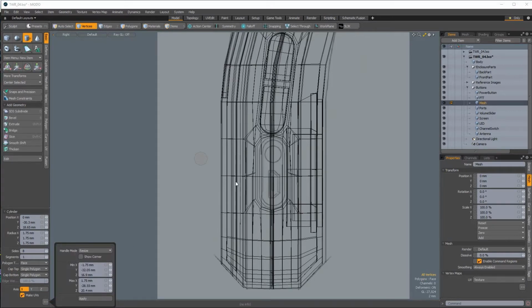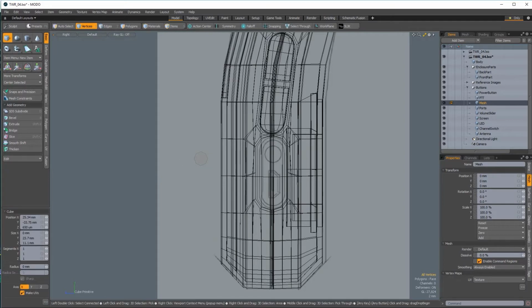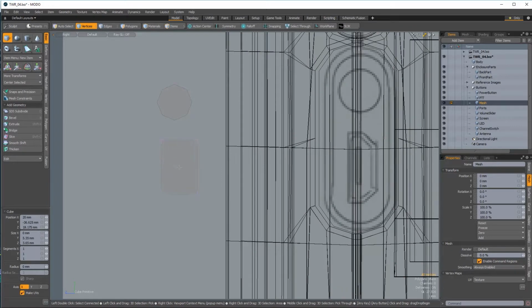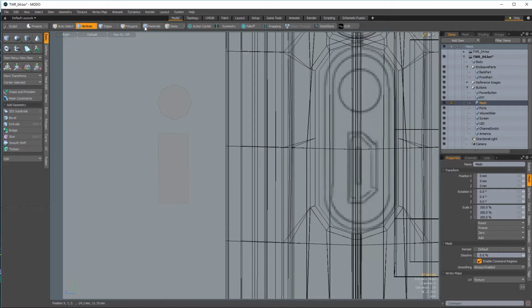So I'll just apply this tool. You can see it's there. Make sure you have a face count that's pretty low, like 8, like I have. And now I'm going to shape out the mini USB port. So I know the basic dimensions of this, so I'll just punch those in here. It is about 6.8 millimeters long and 3 millimeters tall. Spacebar to drop the tool.